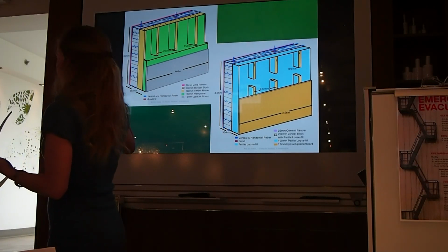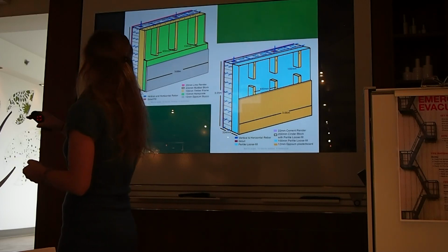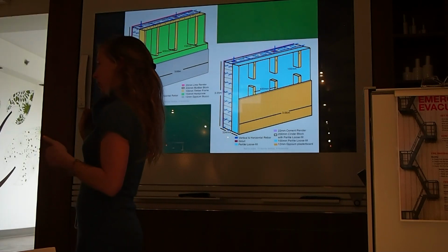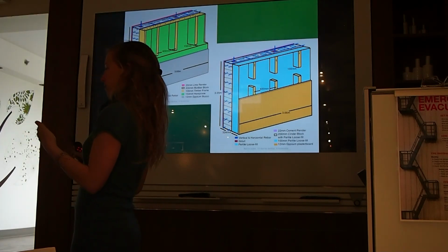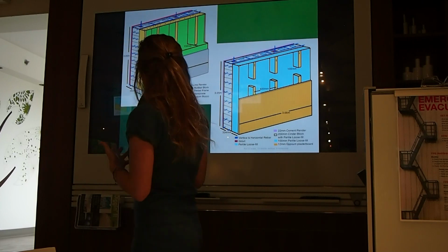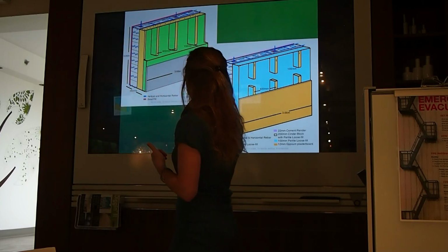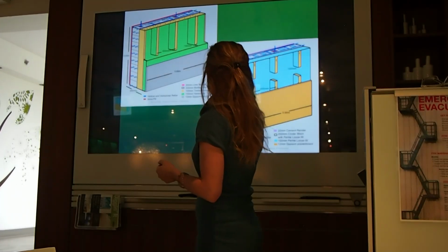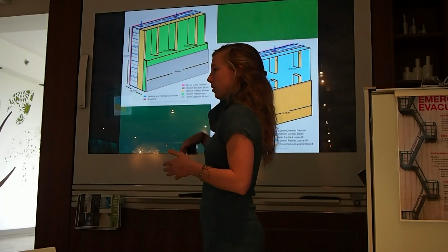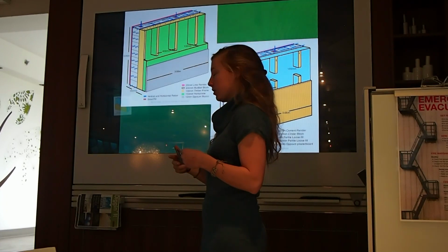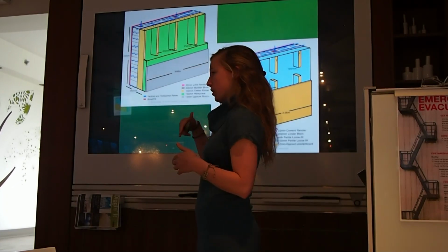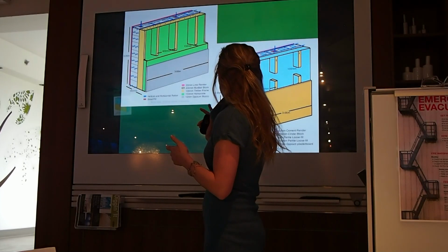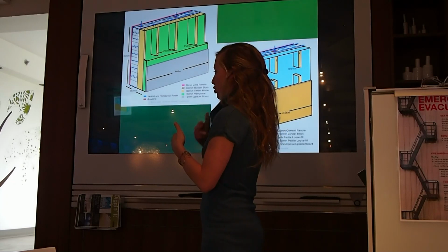So there's a timber frame after the biofiber hemp block, and then the timber frame is actually filled with Hempcrete that extends 50 millimeters beyond the actual wall, and then it's covered with a gypsum plaster. And the bottom right is my comparison product. This is a cement render with the cinder block that are filled with perlite loose fill insulation. Followed by that is a 4-inch cavity with perlite loose fill insulation and wooden timber furrings, and then a gypsum plaster board.